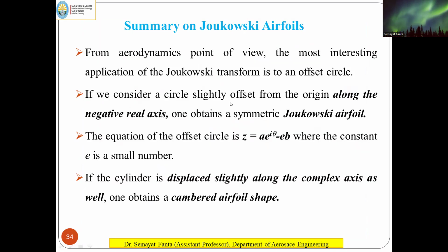So when I come to the summary, from the aerodynamic point of view, if we consider a circle slightly offset from the origin along the negative real axis, that means the negative x-axis, we get a symmetric Joukowski aerofoil.